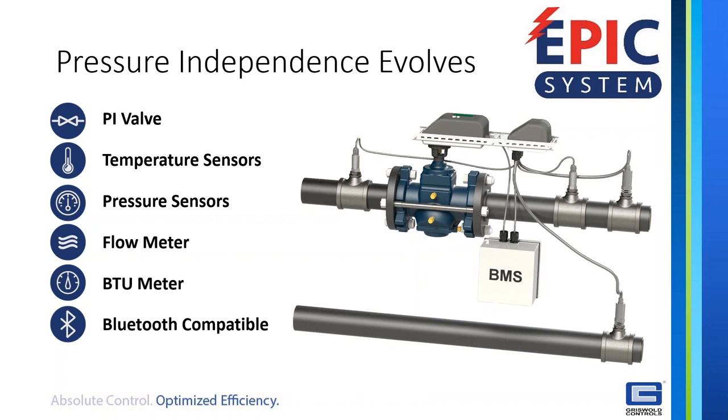We add in temperature sensors. There's a sensor on the inlet to the coil or the terminal unit, and there's a temperature sensor on the outlet. That is where we're measuring what the delta T is. There are pressure sensors before and after our pressure independent valve. That's how we know that we're within the pressure range, and that's how we know what the flow rate is, because the valve itself has the ability to know what the flow rate is.